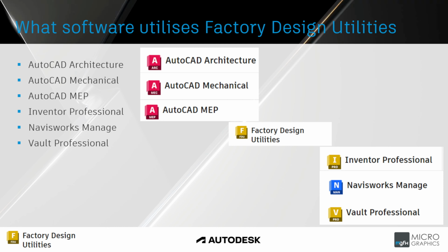And then as well as with a window, so with a door, the door will be situated at the bottom on the floor because that's what a door does. And then when I put a window in, it knows that a window can be placed in the wall. Obviously, it's got to cut out the wall as well, but then I can move it up, down, left or right, wherever in the wall, and it will also provide me that cutout in the wall over there.